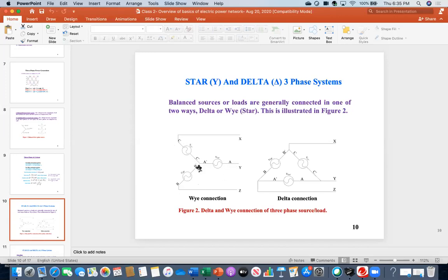This is on, this is on, this is on, neutral on. So then number 4, and another set, that redundant or extra set, just for reliability purposes. In case this set gets damaged, the other set will work. That's why in real practice, over long distances, double transmission lines are provided in case one set gets damaged due to storm or some other factor or maintenance. So three-phase system, 3 coils, 3 lines, and then the neutral line, total 4 lines, and then another 4 lines additional for backup purposes, total 8 lines you might see.